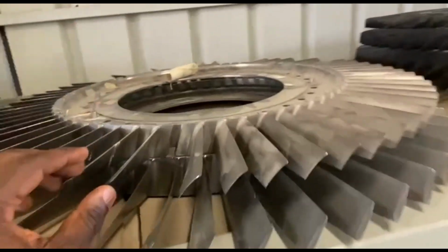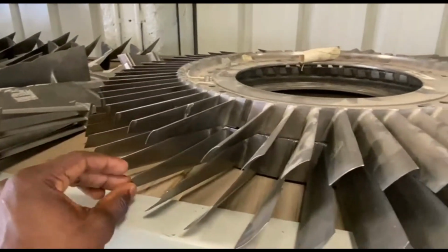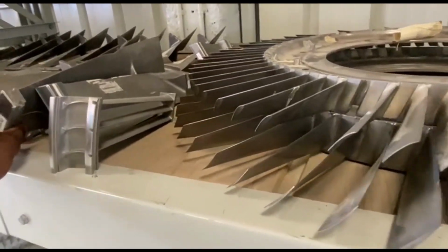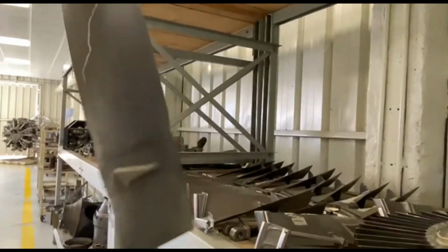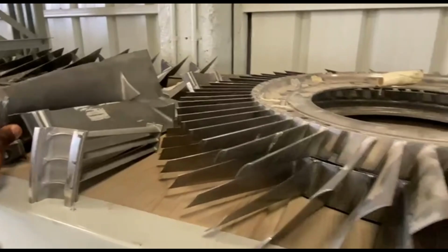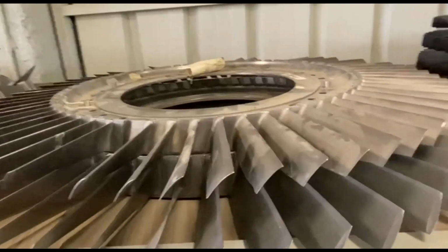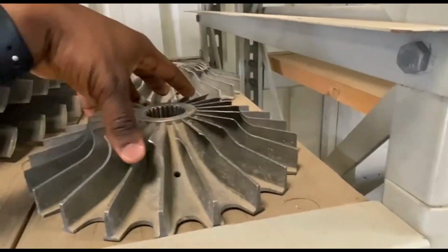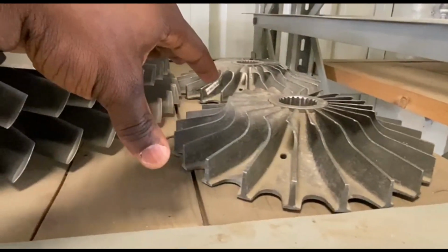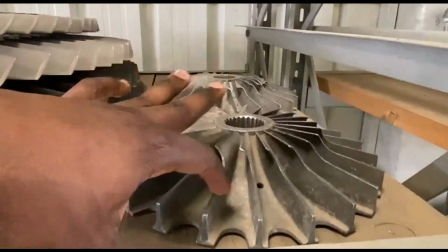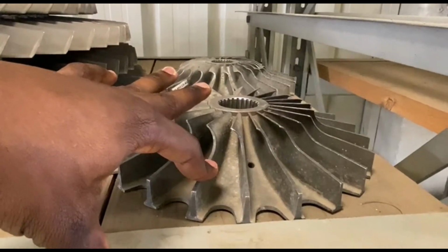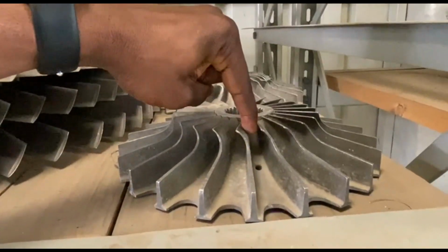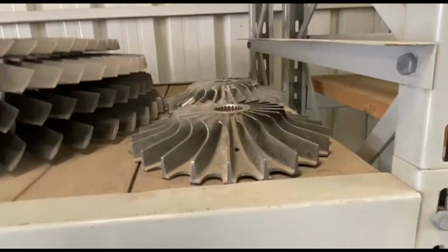Okay, so here we have the turbine blade. The turbine blades are very small compared to the fan blade. The fan blade is huge. You can see the fan blade here. It's very huge, but the turbine one is very small. So this is normally a diffuser part. After the compressor, the air will come here, get diffused, and go to the combustion chamber.